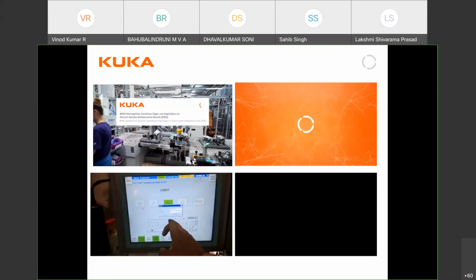So we have set the values. Okay, this is my minimum area and this is my permissible and maximum torques. Based on these torques, the robot or the cobot automatically calculates its own torques. Is it well within the area or well within the region? So this kind of calibration is also done automatically, which cannot be performed in a normal robot.